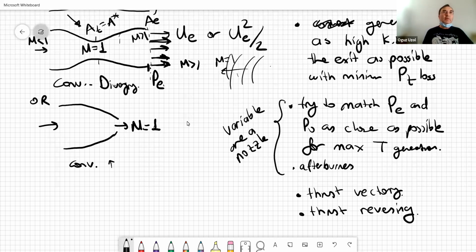Okay. We use this regularly in all passenger aircraft as well. So during landing, for braking the aircraft, quick braking of the aircraft, we put some panels at the back and divert the jet towards the front, so that the momentum change, the almost 120-degree direction change of the jet vector, will slow the aircraft down, because it will create a reverse thrust now. Okay. So that's another system, let's say, integrated generally into the nozzle design. And what else?